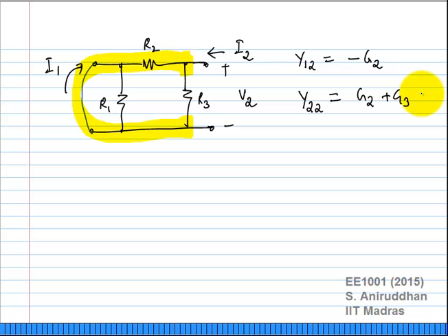So why did we want to write down the Thevenin or Norton equivalent across one pair of ports for any network? Simplify the job of finding out. Exactly. You could take any network and calculate the Thevenin equivalent and the Norton equivalent, or the Thevenin voltage and resistance, or the Norton current and resistance, across any pair of terminals, and use this as a representation of the network across that pair of terminals, for a one-port network.